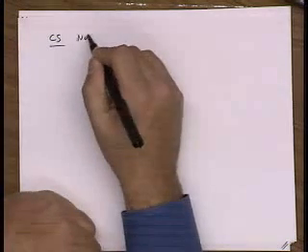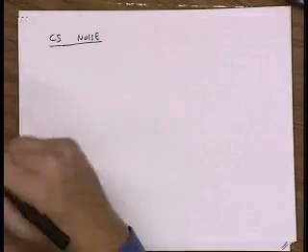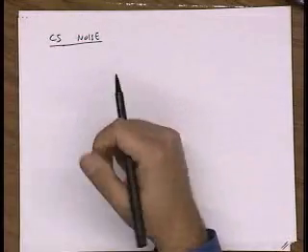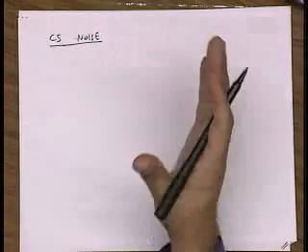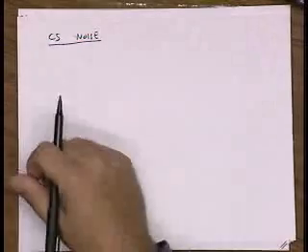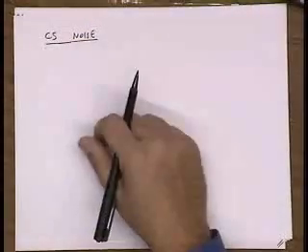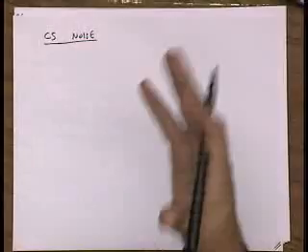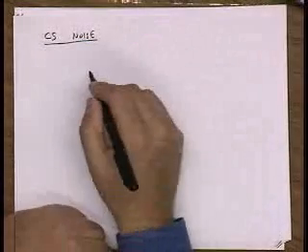Previously we analyzed a common source amplifier, and now I don't want to redo the analysis in detail. What I'd like to do is give you some intuition for where the result comes from. In particular, why is it that we always get something like kT over C? Is it that we're just cooking up examples where the answer comes out to kT over C times something, or is there something more fundamental? Clearly, there's something more fundamental going on.